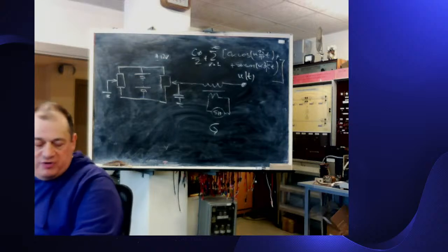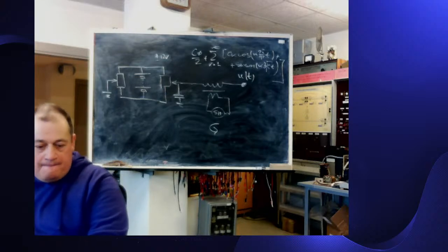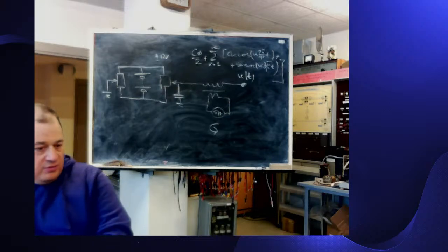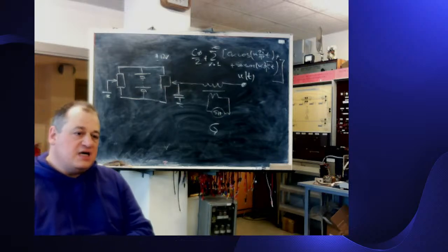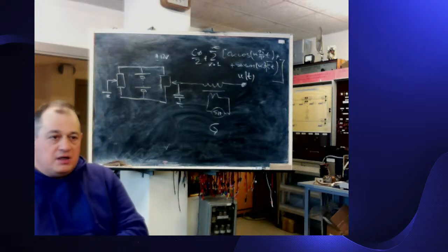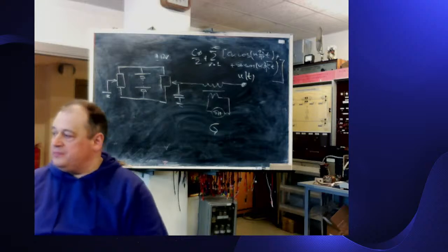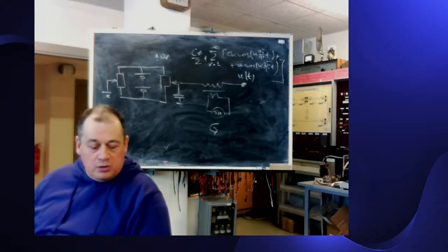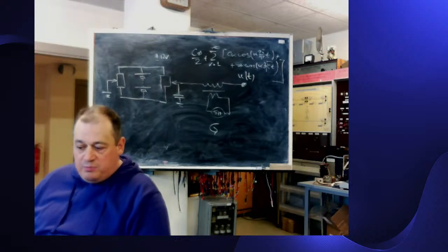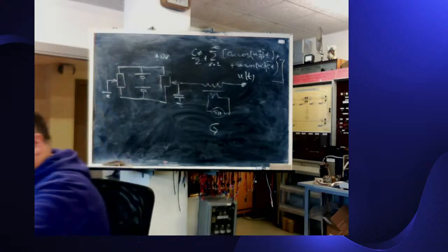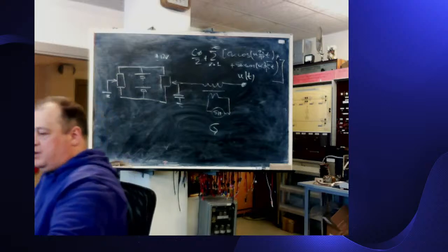All kinds of moving coil with amplifier are only precise on the signal they are calibrated for. Dynamometer, yes, fine. Digital, no guarantees. Only the marked true RMS showed us something reliable.